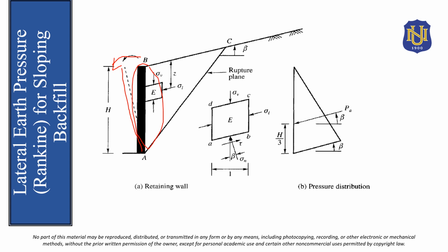So that is an active earth pressure. Then, if our retaining wall has an initial position like this, and it yields inward, that means it is a passive earth pressure, and the rotation is clockwise. So that is still the concept for active and passive earth pressures.